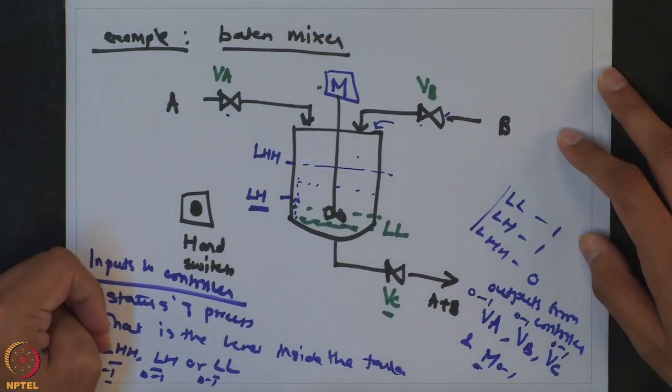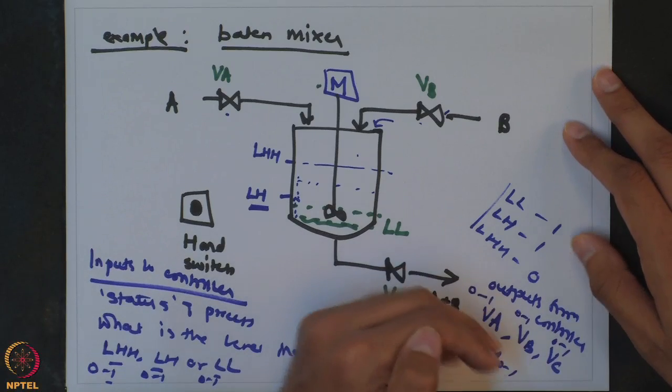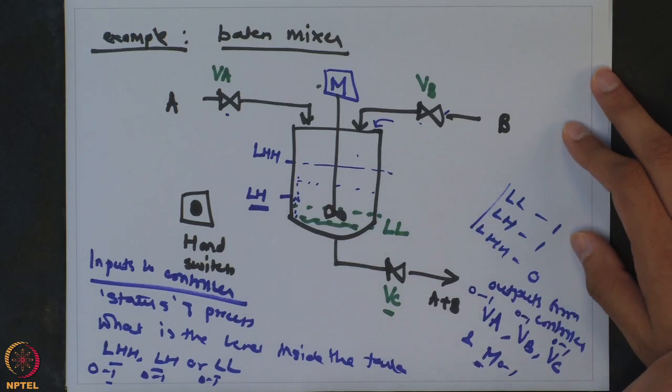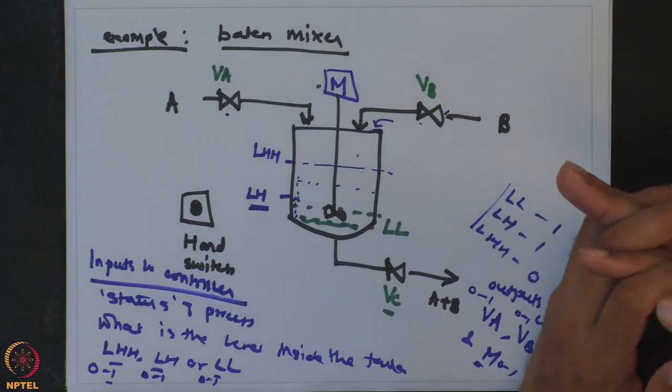Like here you are getting these inputs about the level inside the tank, and accordingly it will give signals to these different valves, which will be executed in the process. Here I am saying that these are mostly binary logic, but it is not necessary. Nowadays these PLCs can also execute non-binary operations in terms of a control law calculation. PID controllers can also be implemented inside PLCs.